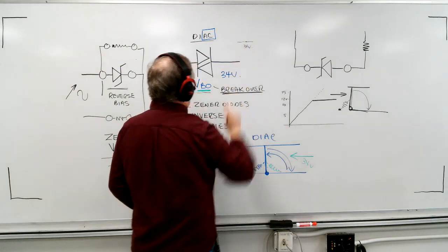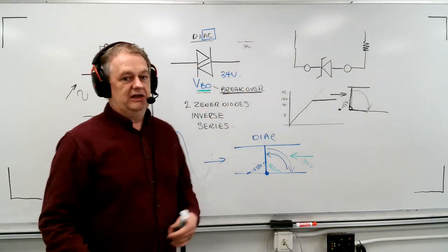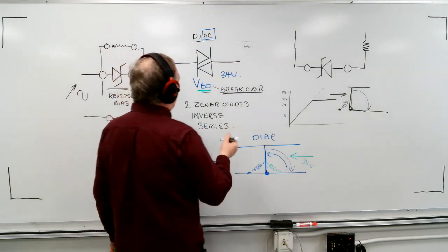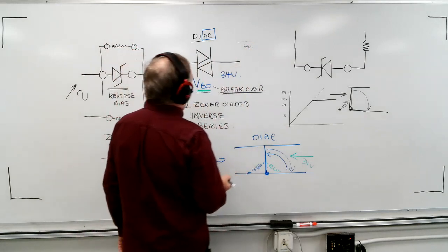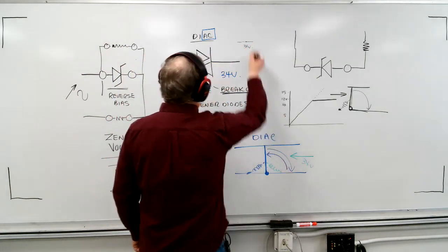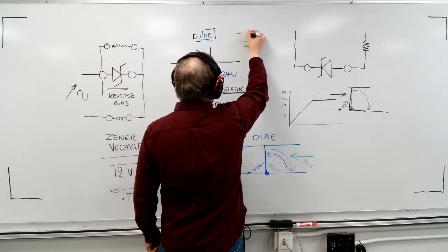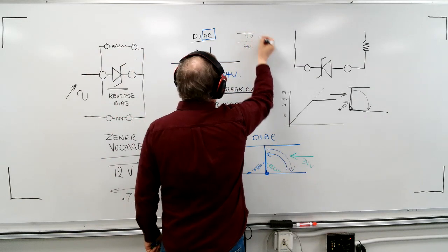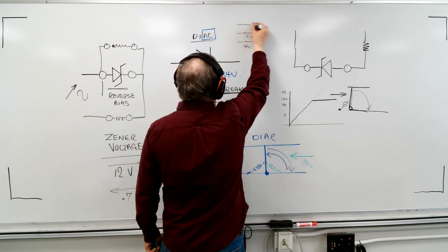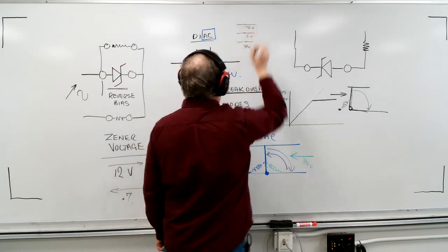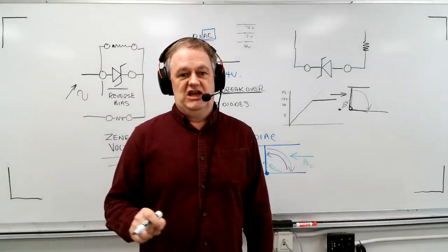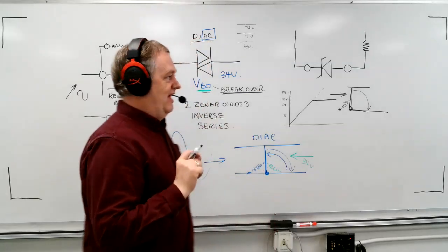Well, that's what you get. You're designing a circuit, and that's what you need. You just buy that diac and you use it. If you actually need a 12 volt diac, then you check your catalog number carefully, and you order a 12 volt. So you can get another diac that is a 12 volt. You need a 72 volt diac, well, then you order a 72 volt diac. Whatever you need, you have to get that specific value, and it doesn't change. It's manufactured in that way.